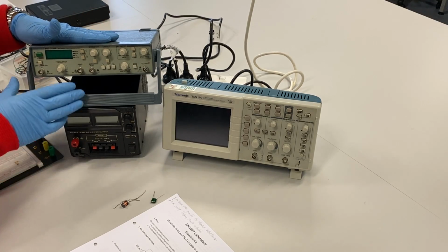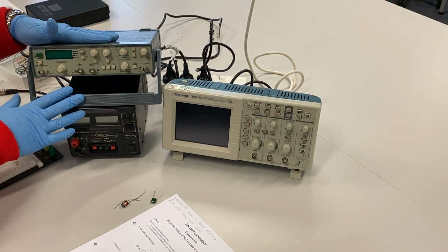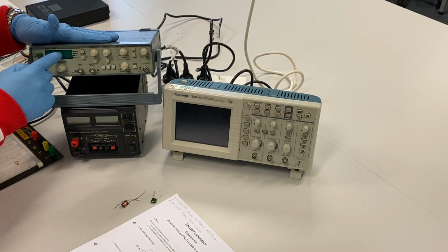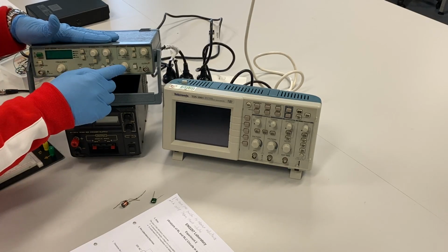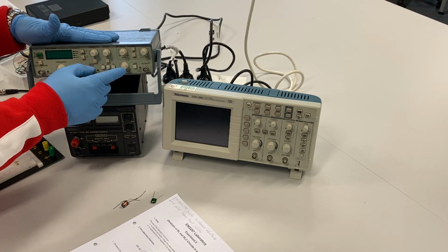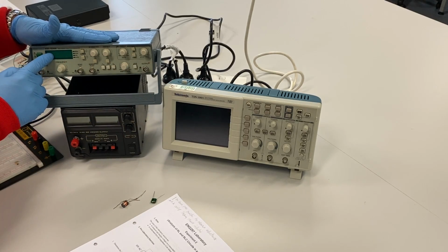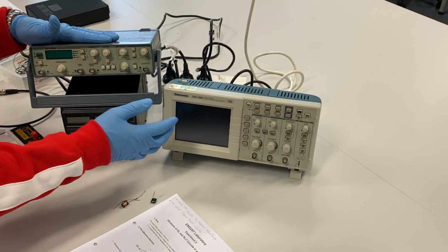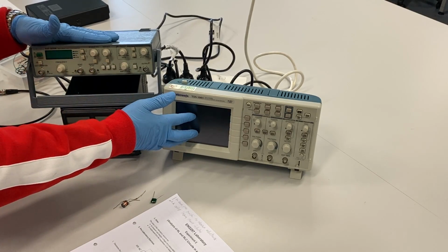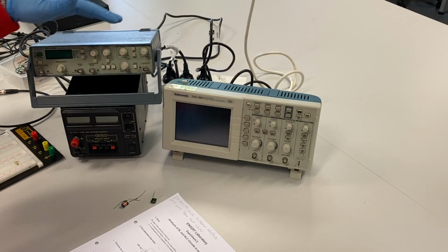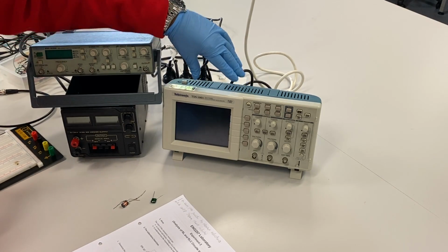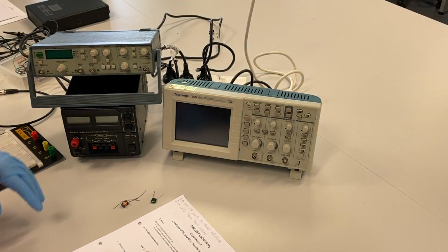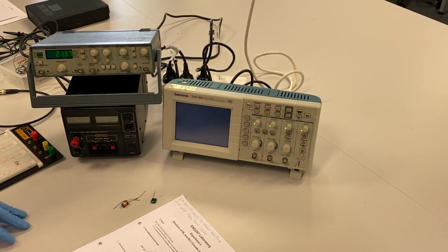But on this particular type of function generator, we can only display certain things. We can only see frequency from here, but we cannot see the amplitude that we're giving in. We need to give an amplitude when we're defining a signal, of course, but we cannot see it here. We can only see it from the oscilloscope. So the other apparatus that we need for this experiment is the oscilloscope. I shall just switch it on quickly. Let me just switch on the function generator quickly as well.